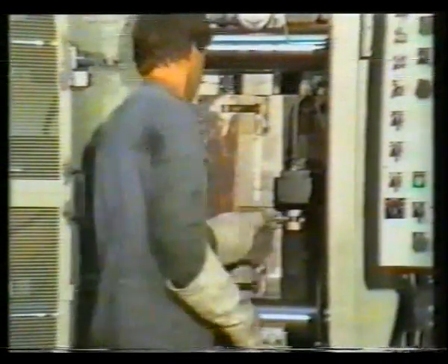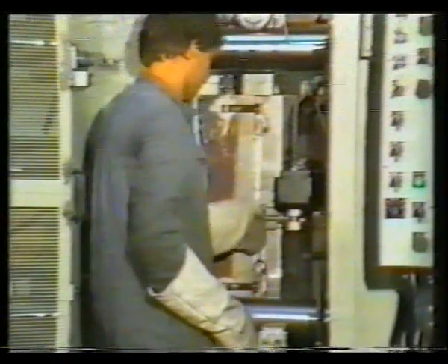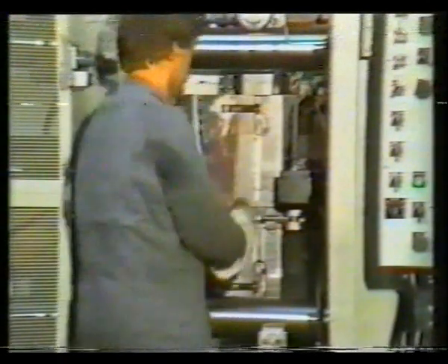Quick switching of production to another rotor type is accomplished by exchanging the middle die plate together with the movable cavity for the short-circuiting ring. The modular rotor die system, too, is provided with quick production change features, including lugs, hinged bolts, etc.